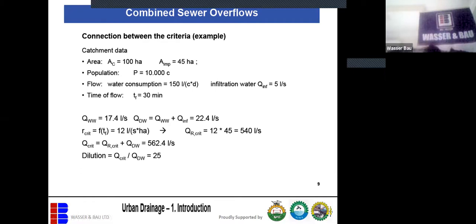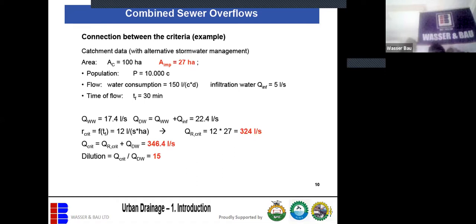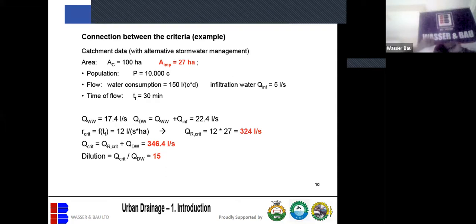So how do you solve it? To solve it, you calculate the wastewater flow. The wastewater flow can be calculated from the water consumption. That is the way to calculate wastewater flow, because it's expected that what goes in must go out. It is expected that if the water board will give you 10 cubic meters of water, you're expected to produce back 10 cubic meters of water, because that is what goes in, what comes out. So when you do this, you get the answer.